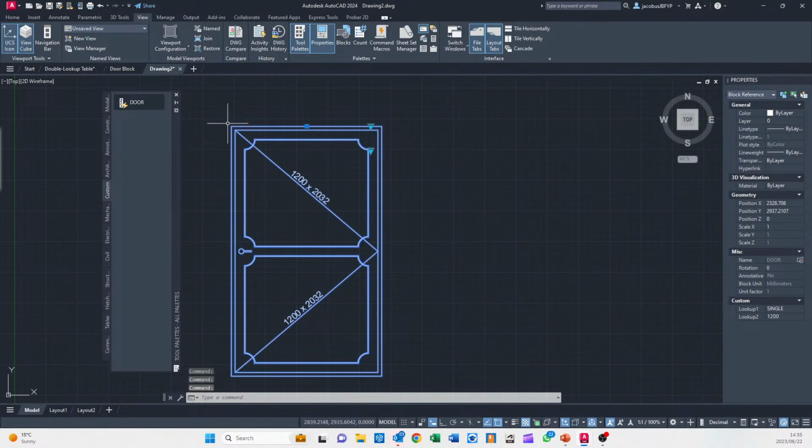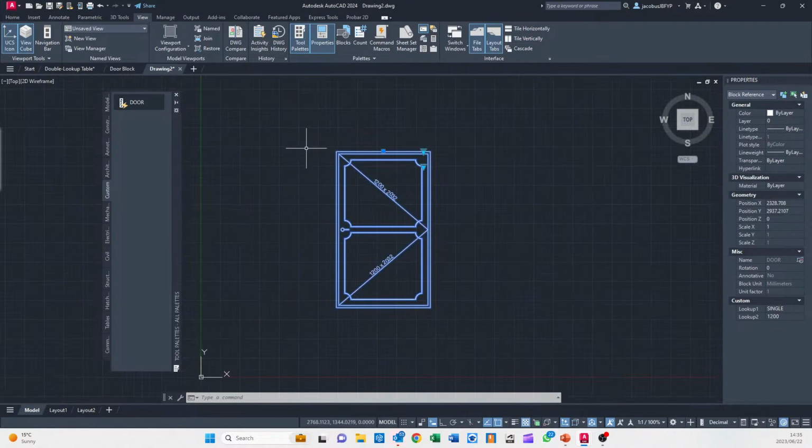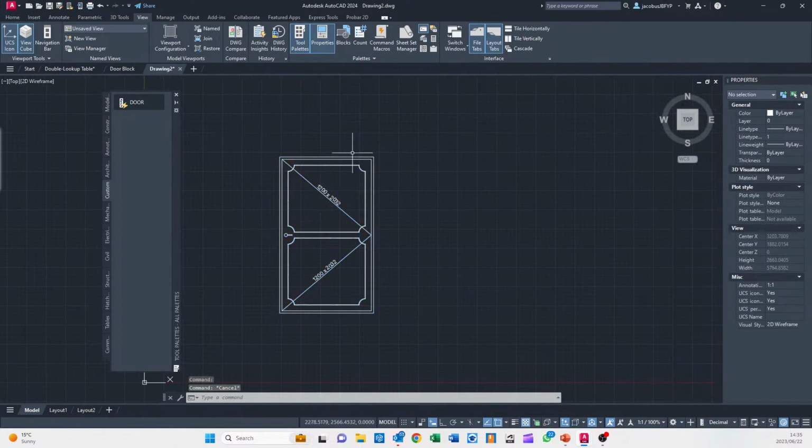You can neaten it up more. You can add alignment parameters, whether you want to align this to the side of a wall or whatever it might be, so that it is easier to place. And remember the BV show command to add that specific alignment to all of the different visibility sets. Just know that in the case where the width changes, you would need to add that parameter to either the top or bottom of this block. Otherwise it's just going to move. I don't think it'll work properly when the width changes.